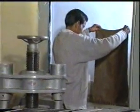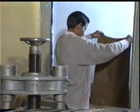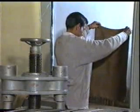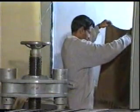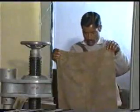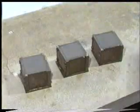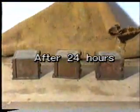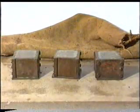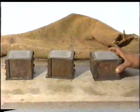After the elapse of initial setting time of cement, which is generally 30 minutes, the cubes are covered with wet gunny bag. This helps in maintaining the relative humidity of 90% and temperature control of 27 plus minus 3 degrees Celsius. At the end of 24 hours, the gunny bag is taken off.